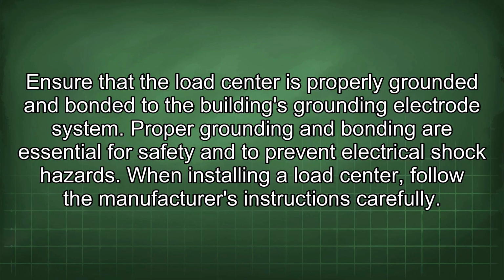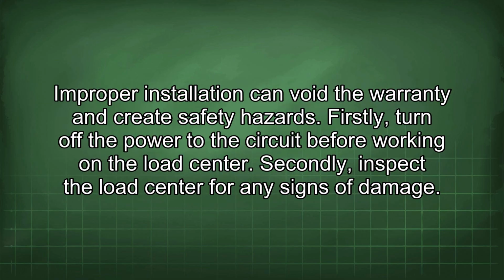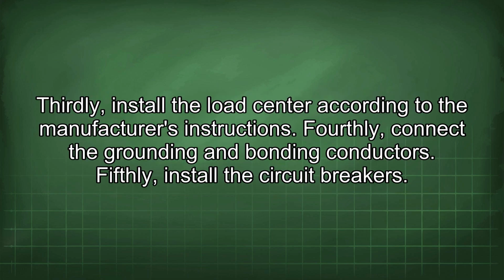When installing a load center, follow the manufacturer's instructions carefully. Improper installation can void the warranty and create safety hazards. Firstly, turn off the power to the circuit before working on the load center. Secondly, inspect the load center for any signs of damage. Thirdly, install the load center according to the manufacturer's instructions.